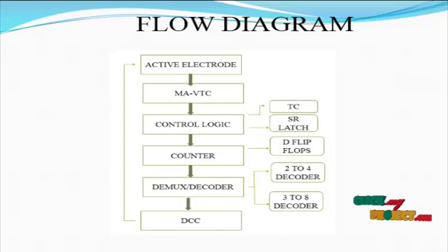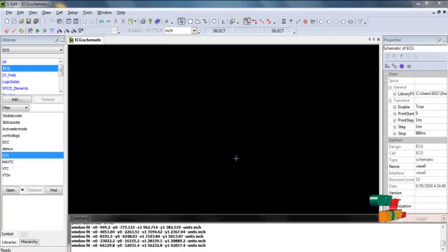The AC coupling capacitors are removed in our product, and the impact of the electrode offset on circuit is cancelled via a feedback loop. The technique used for the offset cancellation is given. An active electrode is an electrode in which some active elements are used to reduce the power line interference. Finally, we are going to see the output for our product.